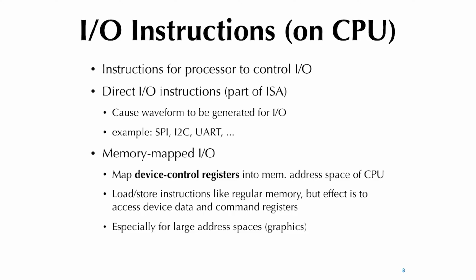They may be assigned by the way the architecture is built, not necessarily the way the CPU is built. Somebody takes a chip, and if you don't do any special wiring, it looks like you have entire memory access, you're not doing any other I/O. But you can also wire up your system so that certain memory ranges correspond to I/O registers.